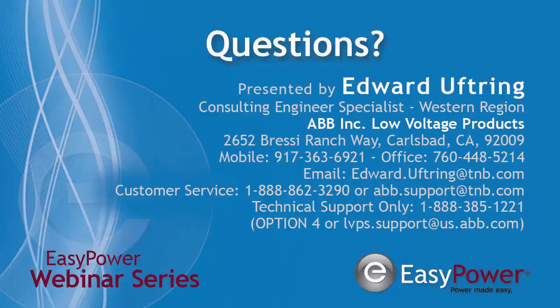I have an 80 amp 3-pole breaker with FD 335K stamped on it. Then interrupt capacity, RMS symmetrical amps, 240 volts 65 KA, 480 volts 35 KA. Please explain these ratings and how they apply to the connected load. So the ratings themselves don't apply to the connected load. What the ratings are giving you here are for the different voltages. You have a different maximum interrupting rating. So at 240 volts, that breaker is only going to handle 65 KA. At 480 volts, it's only going to handle 35 KA. At 600 volts, 18 KA.